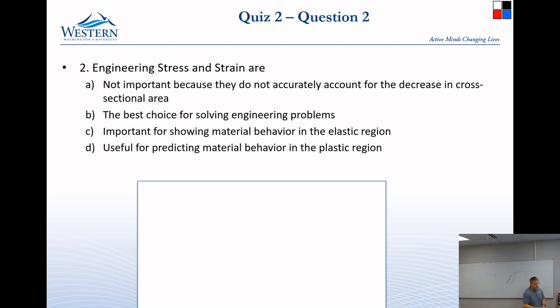When you have sacrificial parts that you're either planning to replace or sacrificing so that your more expensive or problematic parts don't break instead. Okay, yeah, so if you're doing energy absorption for some reason, so the bumper and all of the frame structure on a vehicle, they design into the plastic region because they're trying to protect the people inside, right? And so you sacrifice all of that structure to protect the people inside. And so they will do that design there. Sometimes with other materials you will as well. You will have something that breaks to protect the important part.